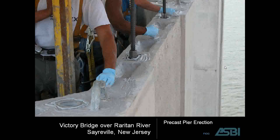Once again, the segment joints are epoxied. The workers place the epoxy on the segment joints. You can see the shear keys and alignment keys for the pier. You can see the ducts for the post-tensioning. These bars, these thread bars, are temporary post-tensioning that allows the contractor to place the segment and then squeeze out the epoxy to achieve the correct joint thickness and geometry.